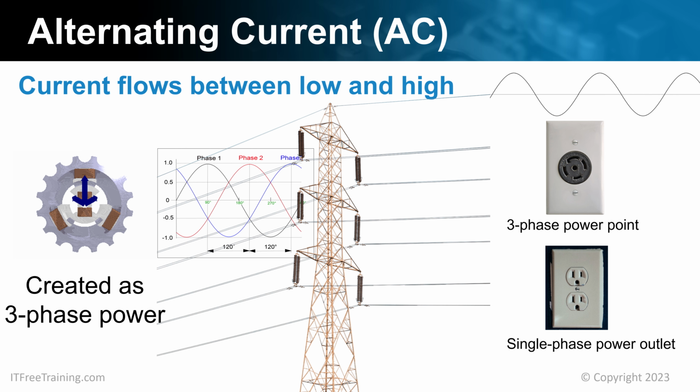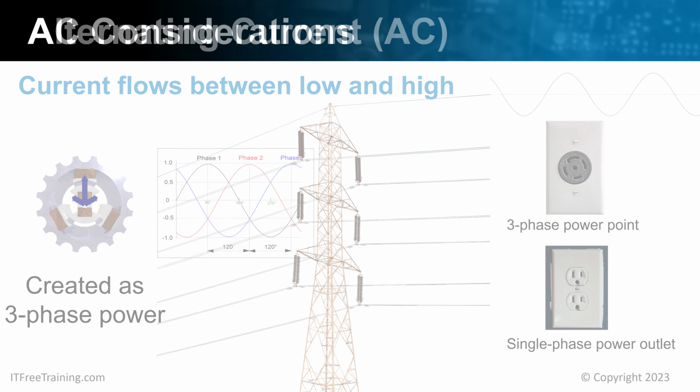Also, since there are three-phase and two-phase power outlets, plus there are also different ratings for the amount of current the outlet can produce, there is too much that can go wrong. So personally, unless an electrician or suitably qualified person verifies it is okay to plug it in, I would not plug anything other than one phase in. There are a couple things that can go wrong with single-phase power, which I will look at next.